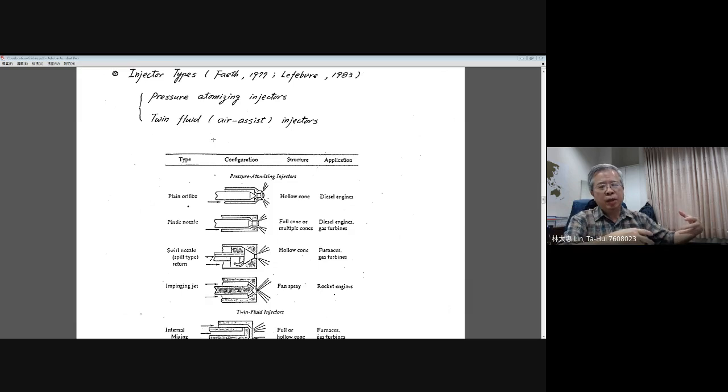Those steam will flow to the steam turbine to drive the generator to produce electricity. Then you can bring a certain amount of steam to our injectors. And steam has some benefit, because steam sometimes has a higher thermal energy, which can help the fuel absorb certain heat for future gasification.